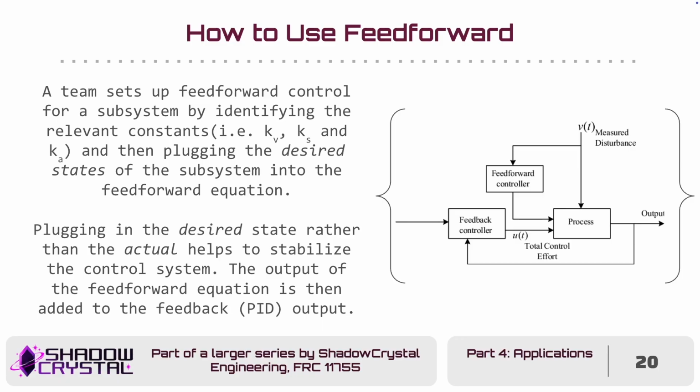And then, once that happens and your velocity increases, what's going to happen? Your feed-forward output is also going to increase. So it's almost this runaway effect, which destabilizes the subsystem and keeps it from maintaining its state effectively, which is effectively the point of feed-forward. So you don't want that.